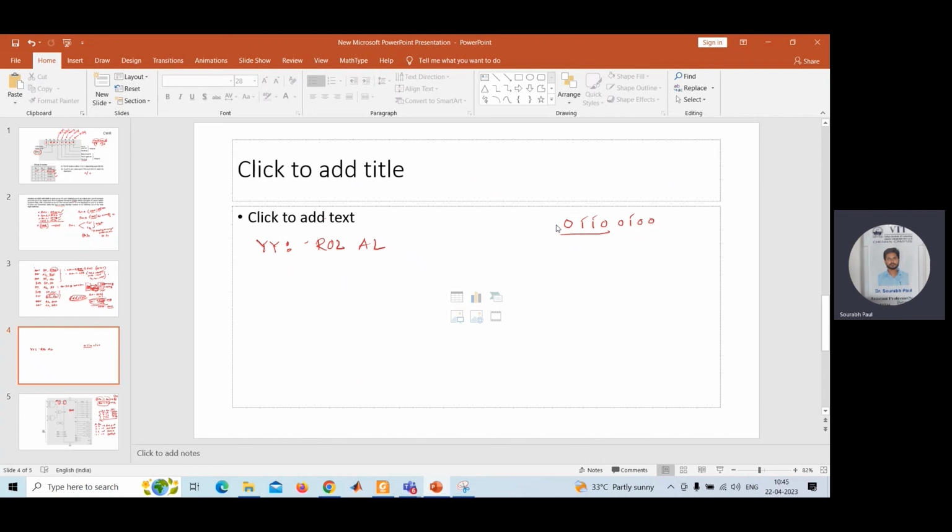So how to check? Every time you can do left shifting on this content. When you do ROL left shifting, whatever the extreme left bit is will come to carry. This is the property of the ROL instruction. So every time you do left shifting, whatever bit is on the left side will come to the carry bit. If you rotate it 8 times, but suppose I am showing the example for 2 times, first rotation, what will happen?